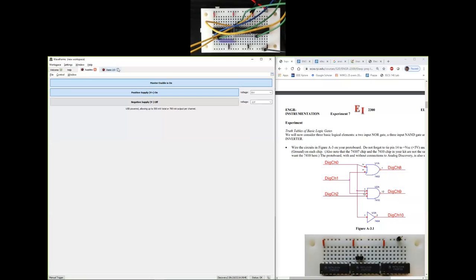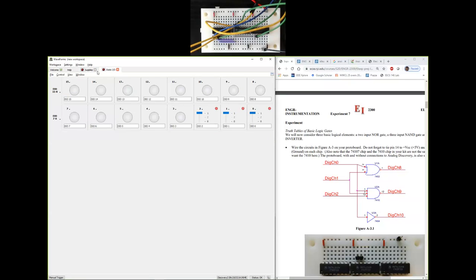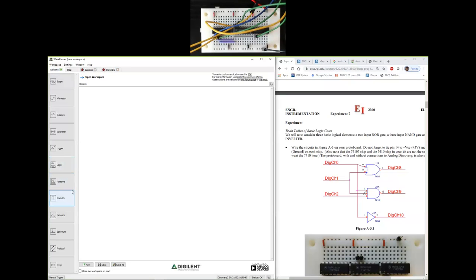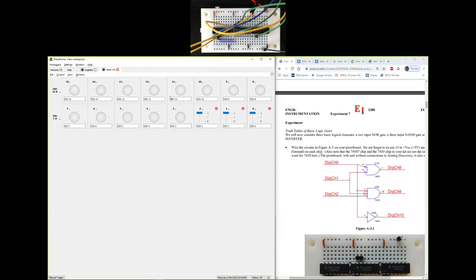I monitor that by using Static IO. If you go in that welcome field, there is a Static IO option. So far in the course, we have been looking at the scope, wavegen, and voltmeter. Now we look at Static IO. As you can see, Static IO brings up this page in which there are 16 options in which I can configure any one to be an LED, which is going to be an output, a button, or a switch of several types.